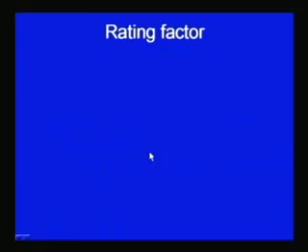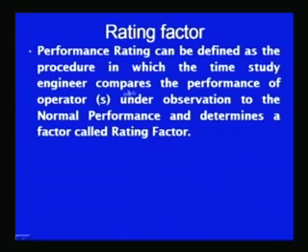the work study man. The rating factor or performance rating is defined as the procedure in which the time study engineer compares the performance of the operator under observation to the normal performance, and that is used to determine the rating factor. So, what is the working speed of the worker, and what is the normal performance expected from the worker? These two are compared to arrive at a rating factor.